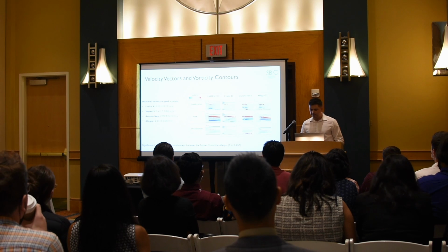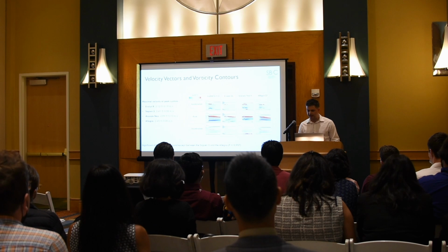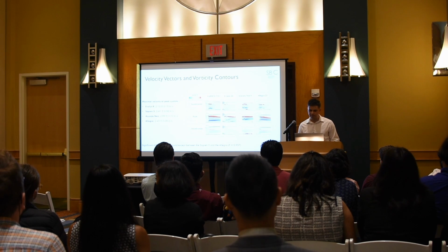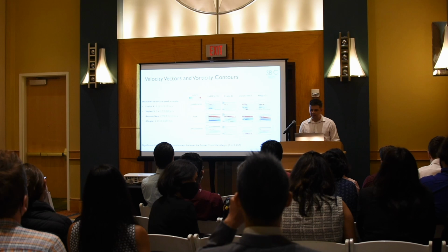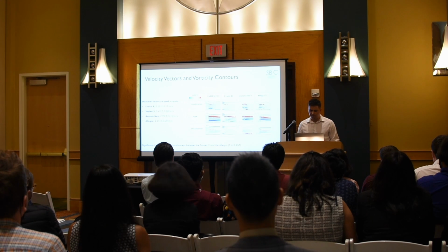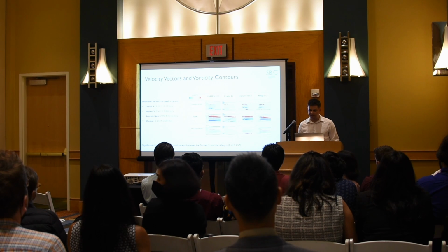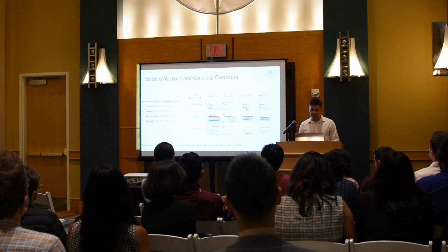So from the PIV, this figure shows the average flow velocity downstream of each valve at the acceleration, peak systole, and deceleration phases. You can see the dark streaks of red and blue vorticity contours, which represent the shear layers corresponding to the jet boundaries, and the distance between them represents the width of the jet.